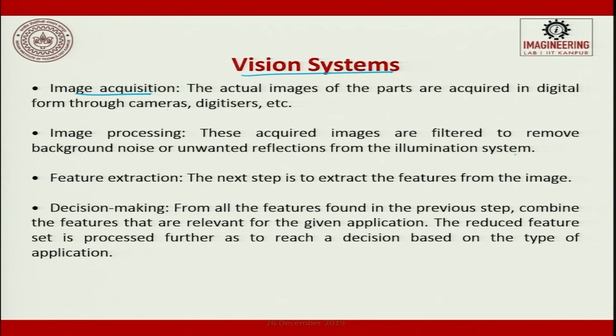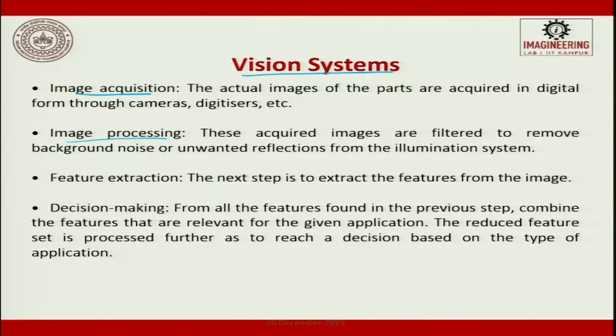illumination system. So, you will have a light which is thrown, because with a camera in the dark, you can't get the image. Even in your normal camera, when you try to press an image, and if it has a night eye application, it will first throw the flash, and then it will try to open the shutter and close the shutter. So, the light that is thrown is trying to illuminate the object. When the illumination happens, you will have the basic image as well as the background illumination effect which is given by the light. So, during image processing, we have to nullify those things and acquire the image. So, that is what happens in image processing.